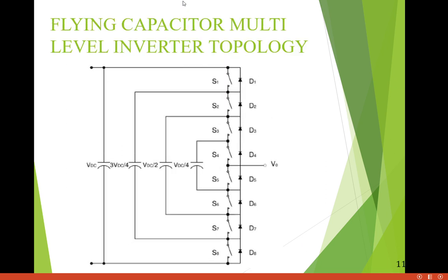And this is the block diagram of the flying capacitor multi-level inverter. The main concept of this inverter is to use capacitors. It is a series connection of capacitor clamped switching cells. The capacitors transfer a limited amount of voltage to electrical devices. In this inverter, the switching states are like those in the diode clamped inverter. Clamping diodes are not required in this type of multi-level inverter. The output is half of the input DC voltage.